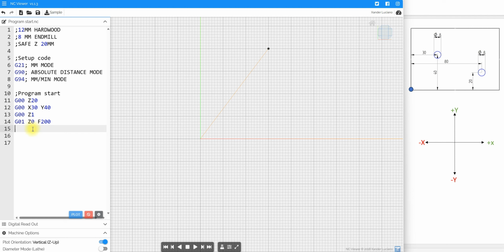So now we are exactly just touching the item, the bracket. So we will now continue. It's a 12 millimeter hole. My plan is to drill down 4 millimeters, then go up, get rid of the chips, drill down to 8 millimeters, up again, get rid of the chips, then down again to 12 millimeters, and we are done. So the process will be G01 Z-4.